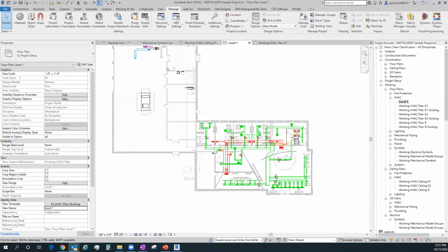So not all errors are going to be errors that cause true crashes. Sometimes it'll just kind of mess you up for a little while and not necessarily do anything to anybody else, because maybe you've killed Revit, but you didn't save and sync, so it's not really pushed into the central file at that point. So usually I don't worry about those too much. I do want to find out what the error code means and why.